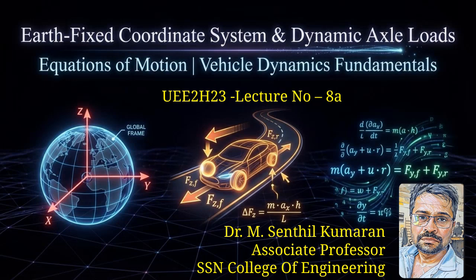An inertial Earth-fixed coordinate system is required to write Newton's equations for vehicle motion. Measuring acceleration relative to the ground allows accurate prediction of vehicle behavior. This includes weight transfer, stability, and control during braking, acceleration, and cornering. Using the Earth-fixed frame ensures that vehicle dynamics correctly represent real driving conditions on the road. Let's begin with how vehicles are represented mathematically in an Earth-fixed inertial frame.